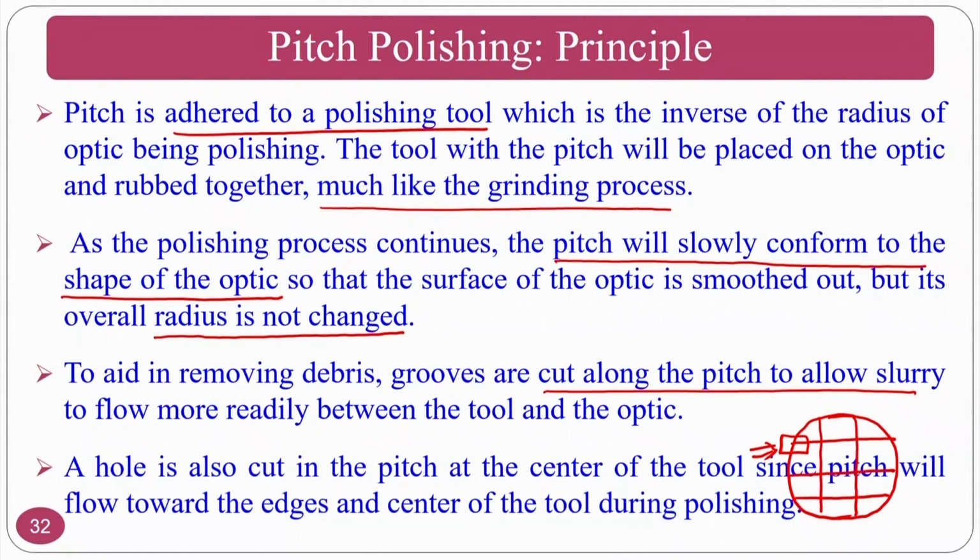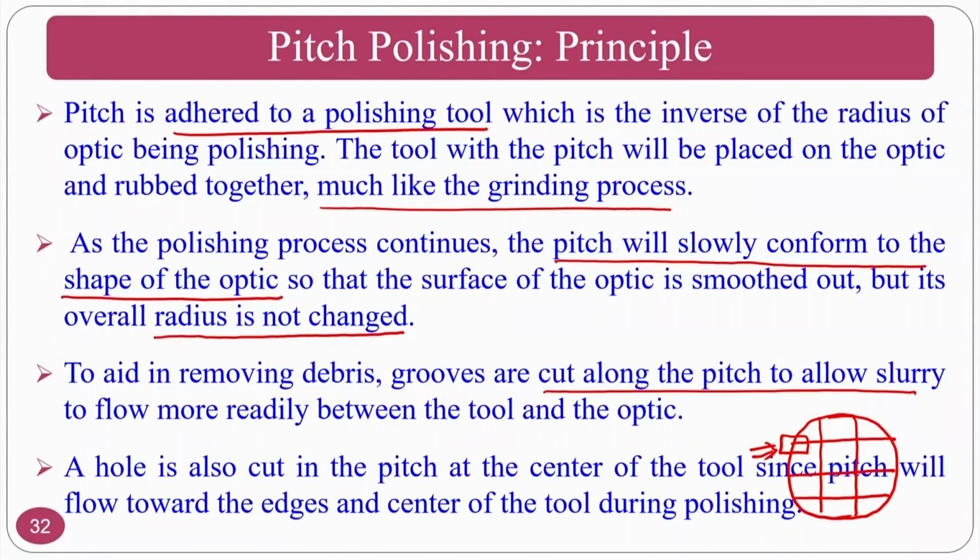The hole is also cut in the pitch at the center of the tool, since the pitch will flow towards the edges, the center of the tool during the polishing. That means that there will be a hole. So what I mean to say is that the pitch tries to move out towards the edges, or towards the center. For that purpose you will have a hole at the center.